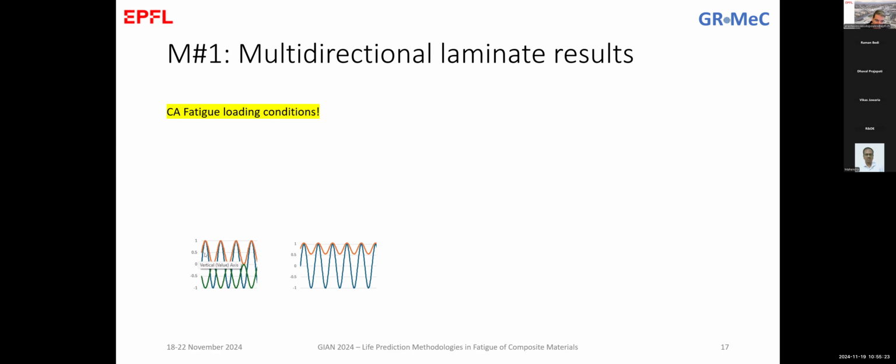We can also have this orange spectrum here, which goes from 0 to a maximum value. And in this case, the stress ratio is 0 over something, which means that it is 0. And this is tensile loading, only tension to the material. There is also another case that we did where we went from 0 to minus something. So it is always a compressive loading. And in this case, the stress ratio is minus something over 0, which means that the stress ratio here is infinite.